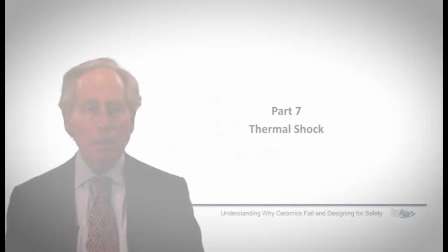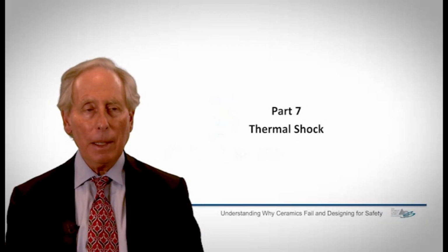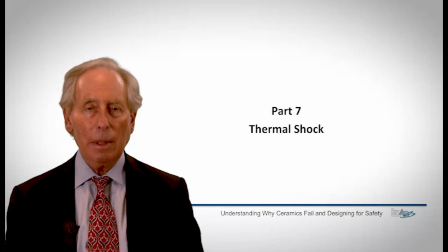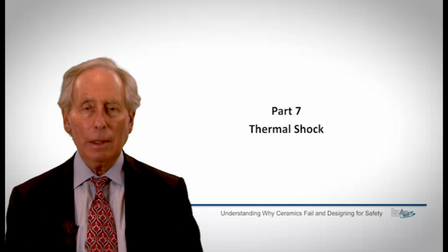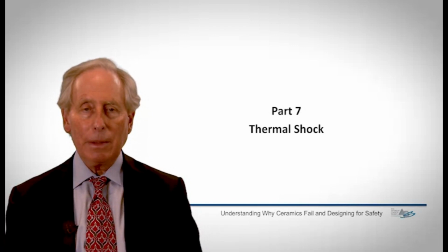Next section I want to talk about maybe a little different topic. It's not so much material dependent as test dependent, but it's very important in the use of ceramics because of their sensitivity to rapid changes in temperature. And of course, for many people, this is the way that many ceramics fail because they were quenched too fast. You put them in cold water when you shouldn't have.